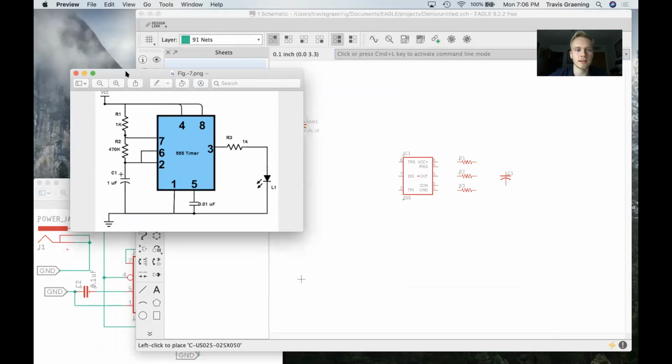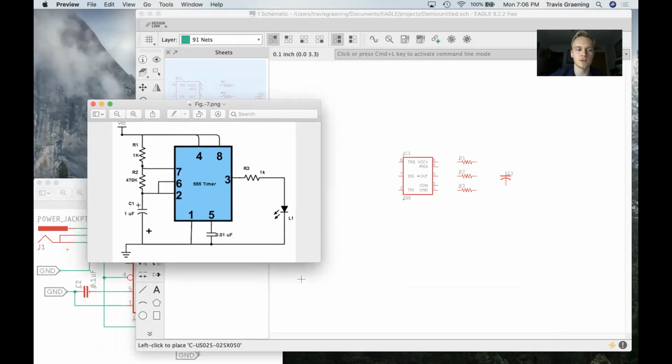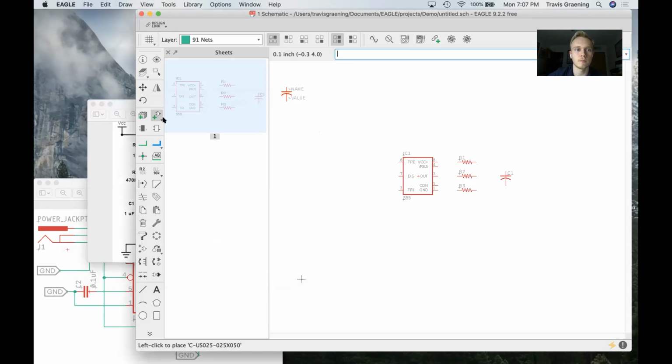Now it's worth noting that there are capacitors which have polarity, like this one, capacitor 1 in our schematic. And those, you can see it has a plus sign next to it indicating the side which is positive. And there are ones that are non-polar, like this one that's connected to pin 5 over here, and that's just got 2 straight lines. So technically it doesn't really matter at this point which one we're using if our footprint is correct. But let's find an electrolytic one next.